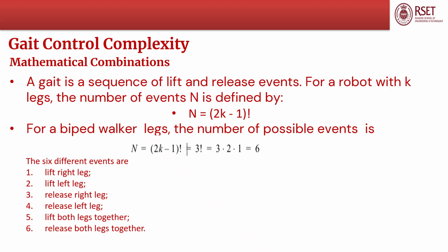Another very important term in leg locomotion is gaits. Gaits are the repeating patterns of leg movements. Each gait is defined by which legs are on the ground at each moment. To walk safely, a leg robot must keep its center of mass within the support polygon formed by its feet on the ground. For example, when a hexapod lifts three legs to step, the other three form a triangular support polygon. Control of leg robots involves planning of foot placement and coordinating joints so the center of mass stays within that polygon.